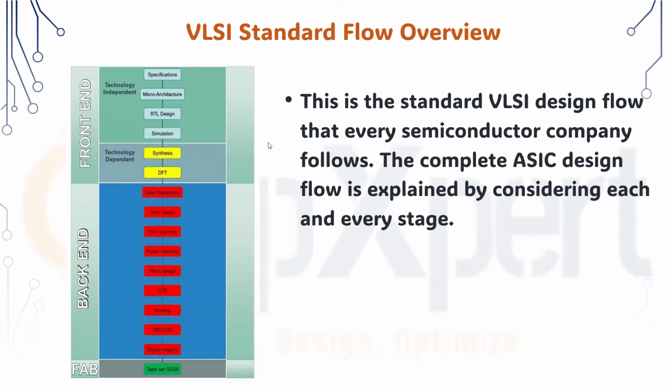The synthesis stage will assign each gate to a particular standard cell. Let's say you have an imaginary gate, but it has to be physically present in our chip. For that, the layout team will design a particular standard for that CMOS. Basically, they will create a CMOS for each of the MOSFETs, whether a FinFET or a GAA technology, whatever they use, and convert it into that standard cell format for each cell, and submit it to the backend team.